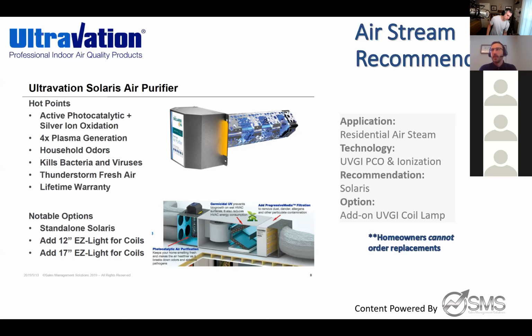If the ozone's an issue, recommend the Catalyst. And if they still want that ionization, then you would recommend something like the Orion. The Orion's going to give you ionization, which you would mount right before the air filter. So we're going to probably get into that next, I believe.